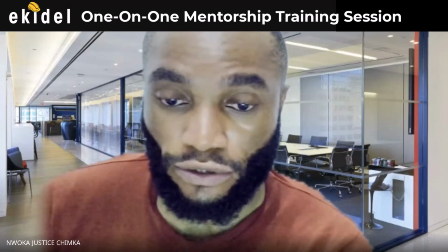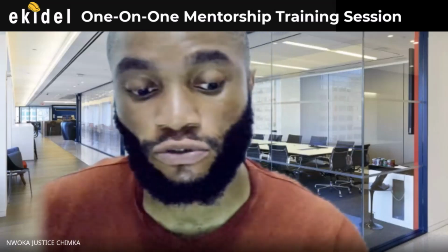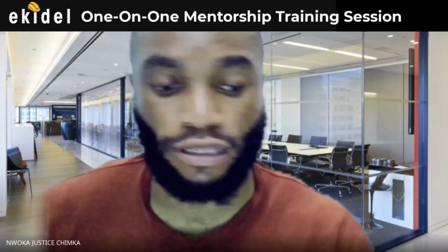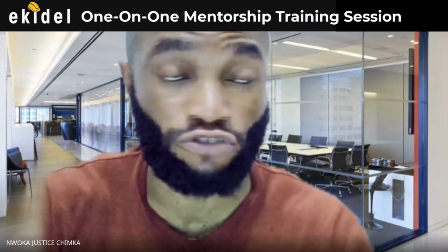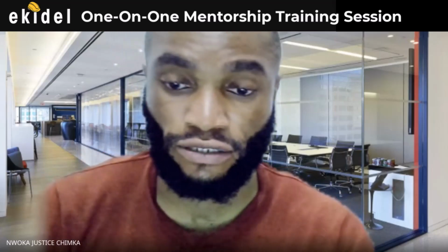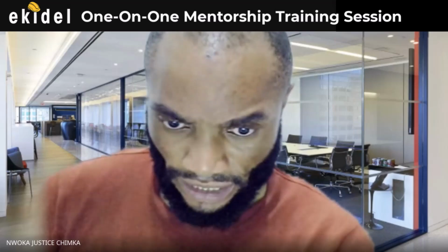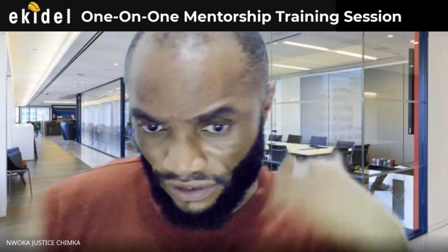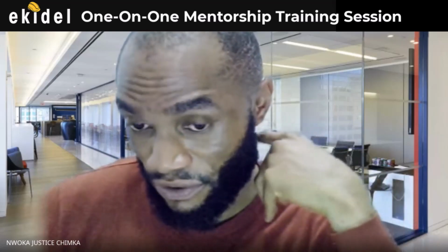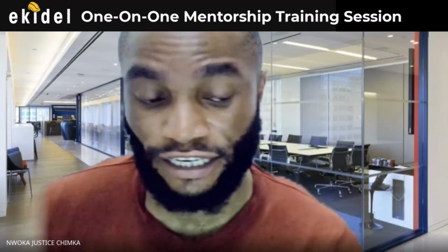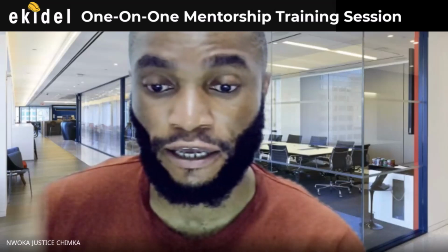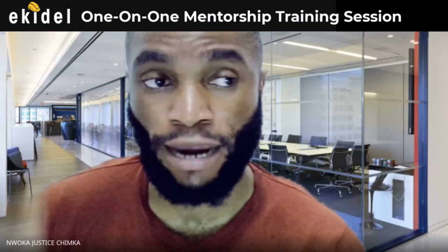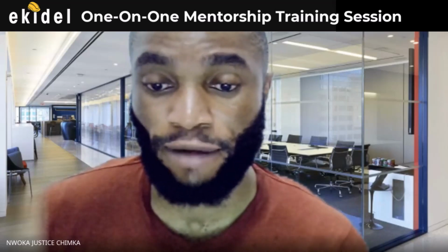Then number of piles, we can say minimum is 1 and the maximum, since this is a small structure, we can say 10. It's not a big structure. Then you can leave this one as default, then this one too as default, for us to have like 3 different pile arrangements in a pile cap here.